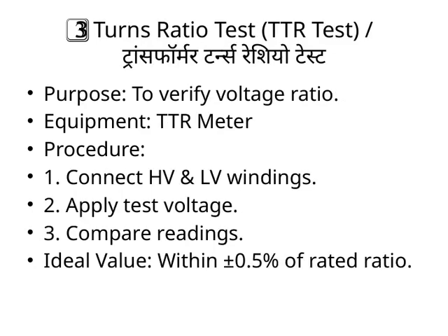Let's talk about the turns ratio test, or TTR test, which is also known by its Hindi name. The main purpose of this test is to verify the voltage ratio of the transformer, ensuring that it matches its rated specifications. To perform this test, we use a TTR meter, which is specifically designed for this purpose. The procedure is quite straightforward.